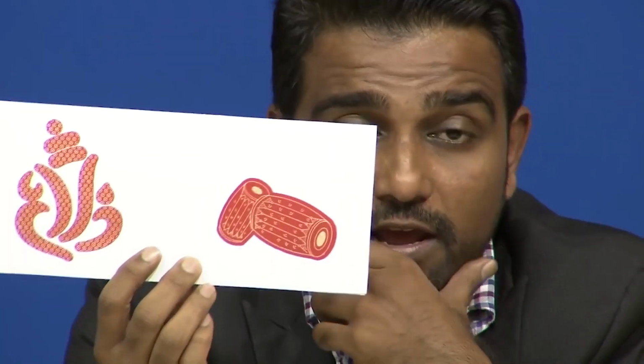There is some kind of step, right. The step is there because the film thickness is very large compared to thin film. So what I am showing here is nothing but a thick film technology, and the material can be an insulator; we do not need a conducting material here, is it not. But in the case of integrated circuit technology, it can be a resistive material, a dielectric material, or a conductive material with different properties, right.